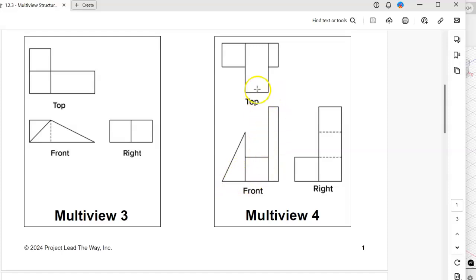So we've got what looks to be a rectangular prism that's represented by this square here in the front view. That does look to be twice the depth of the other features because it's protruding out. That's what creates this visible edge as well as this visible edge, because it's not flush with the other 2 objects. Looks like I've got a flatter rectangular prism that's up on its end. It's sticking upright. That's just sandwiched on the base on one side, and on the other side that looks to be a right triangle that we've done before, where the point is going up into the air.